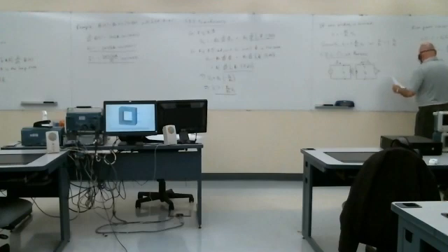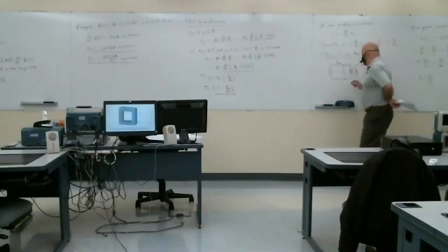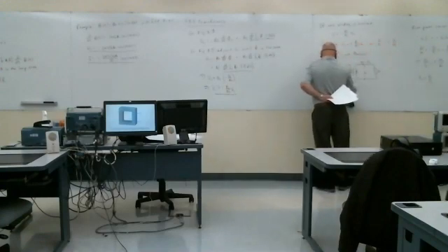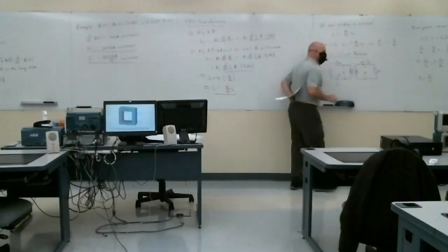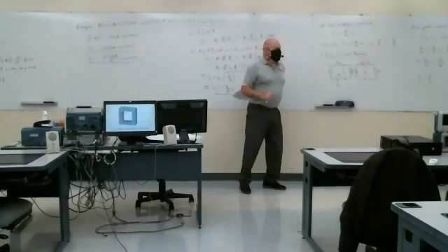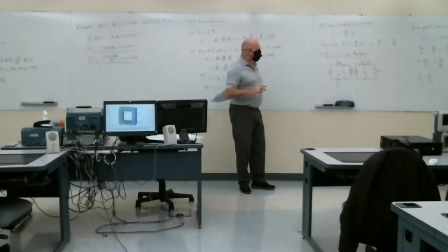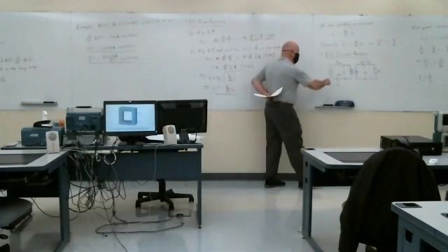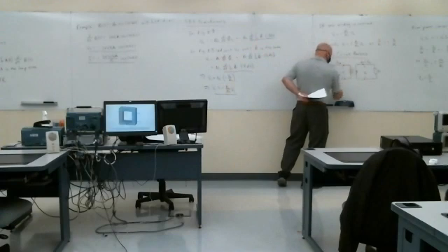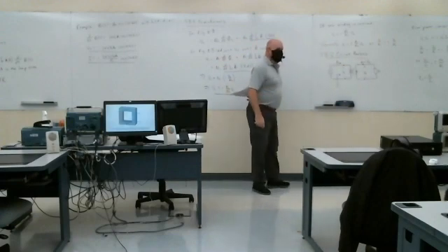You can also get a direct relationship between the impedance seen looking into the primary. So we could replace the transformer and the load, as far as the source is concerned, with this equivalent impedance. That's what this Z1 represents, and it's the ratio of that voltage to that current. So I could replace everything to the right of this pair of terminals with this Z1 impedance.